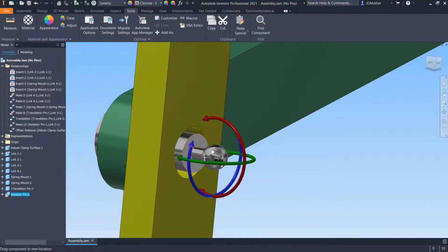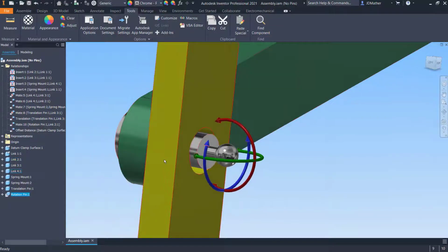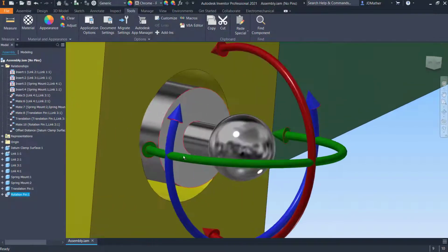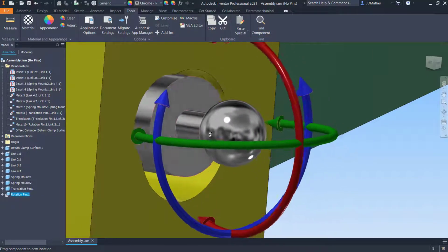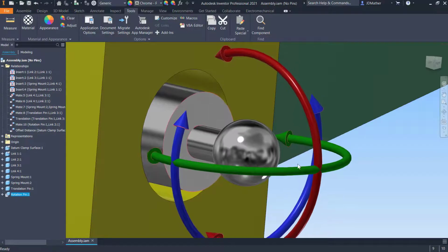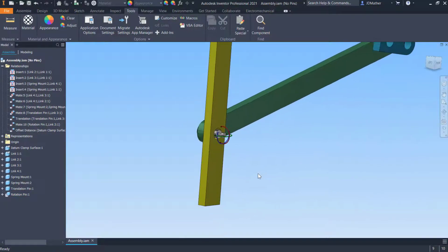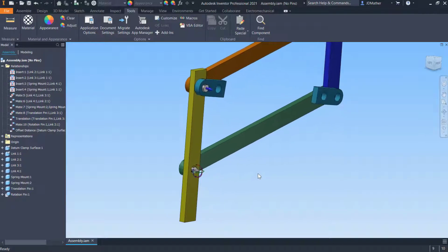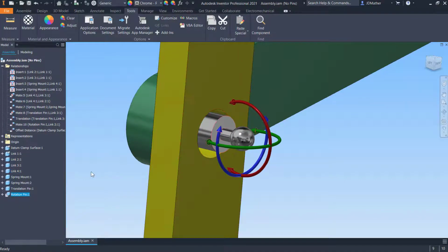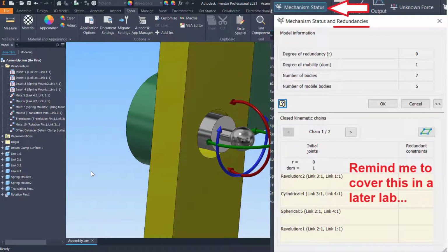along X, Y, or Z, or if this pin is connected to that. In any case, maybe this part will be able to flex, rotate around its axis this way slightly. Now I've really exaggerated that motion so that we could clearly see it, but we have to have that clearance in here. And so in the CAD program we can fudge these just like not putting a pin in here, but we need to account for the realistic motion, or otherwise we will get an over-constrained condition in dynamic simulation.